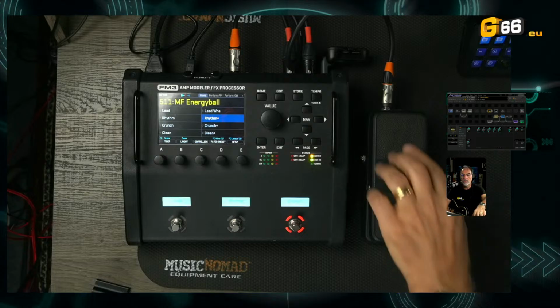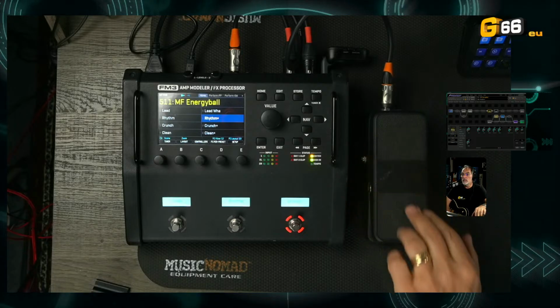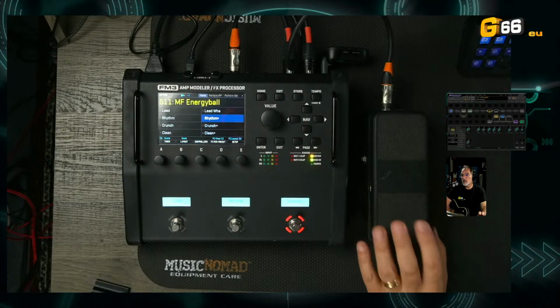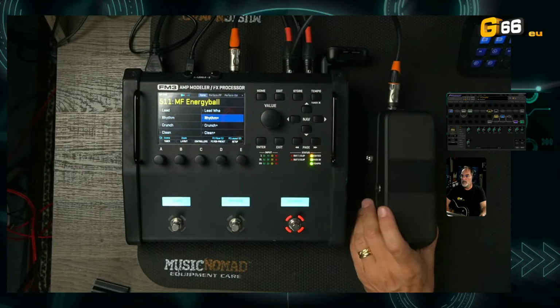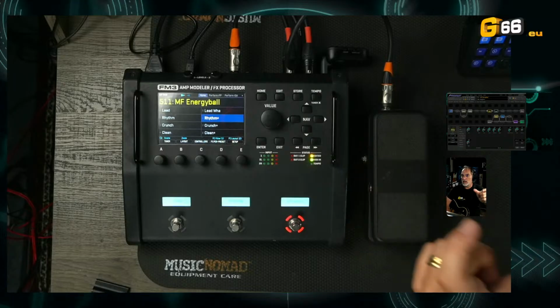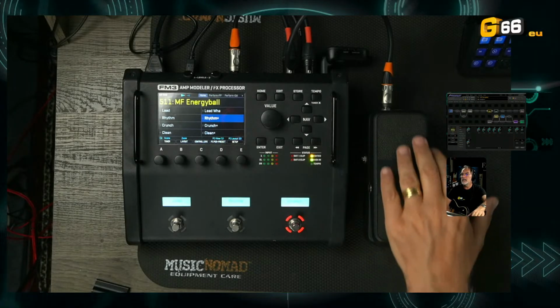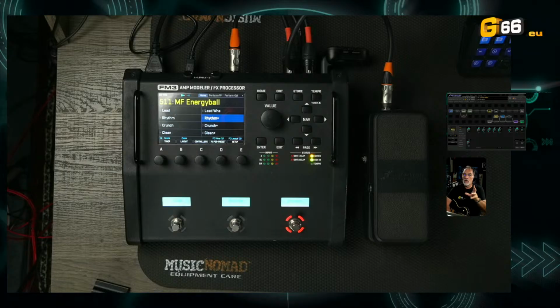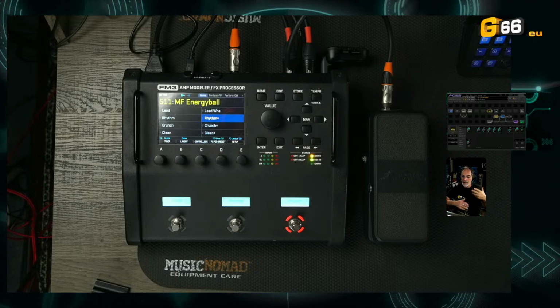I will explain. Then you affect the sound of your guitar with the impedance of the pedal, because the pedal is a potentiometer. There is a potentiometer inside, and this potentiometer gives a small impact on the sound. Typically, the sound is darker than the standard sound, because it is a physical component, there are resistors inside, and resistors cause an attenuation of the high frequencies.